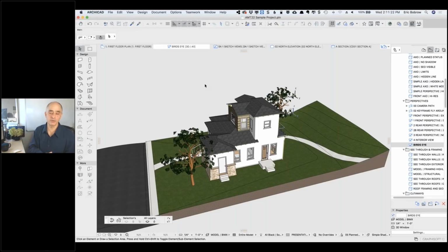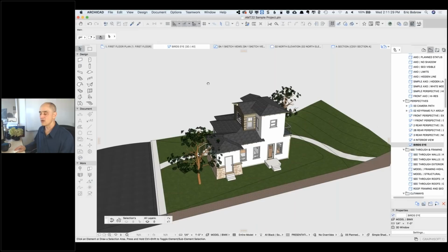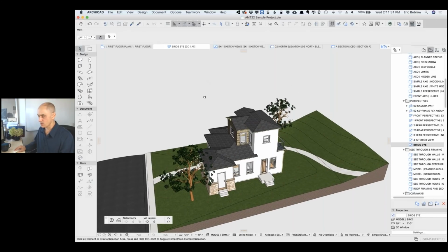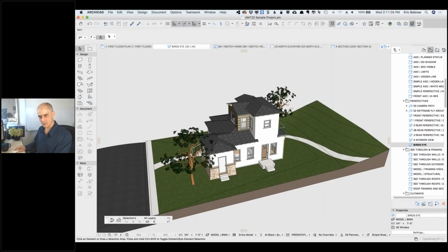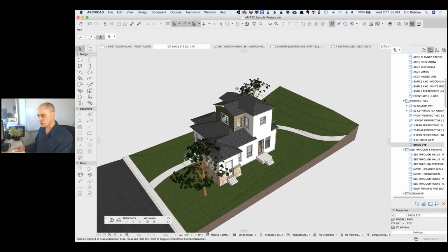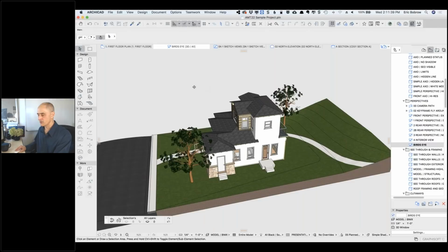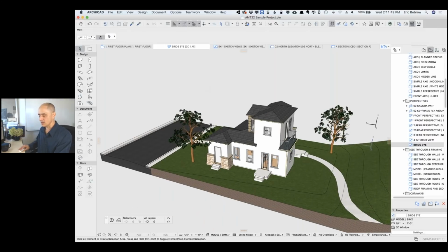And in fact, a quick tip for moving around in the view is, you press down the center mouse button, you can move left or right. That's panning, or up or down this way. If you press the shift key at the same time, we're in orbit, and I can rotate around to different viewing points. It's the same thing as using that orbit thing here, but it's just quicker. Center mouse button, press down, shift key gives you orbit in 3D, allows you to just reposition on the fly. Very convenient.